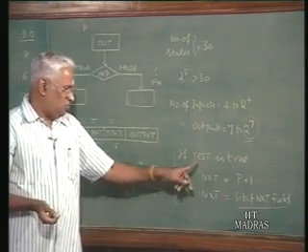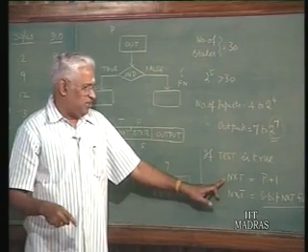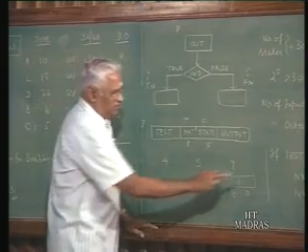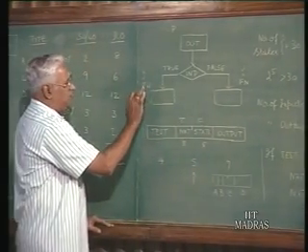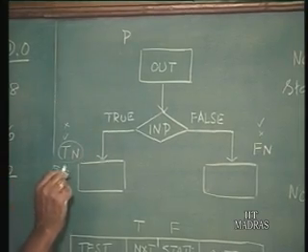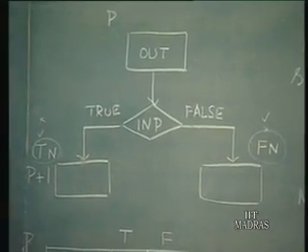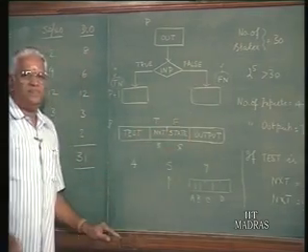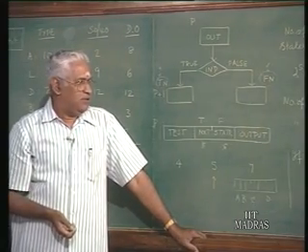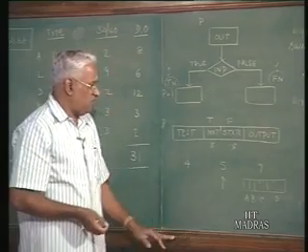If the test is true, this has to be designed in. The next state will be automatically the present state P plus 1. So, as I have formed here, this code for T n will be P plus 1, that is the next one, whereas this false next state will be indicated by the 5 bit field. That is what this particular thing is. Agreed? Good.